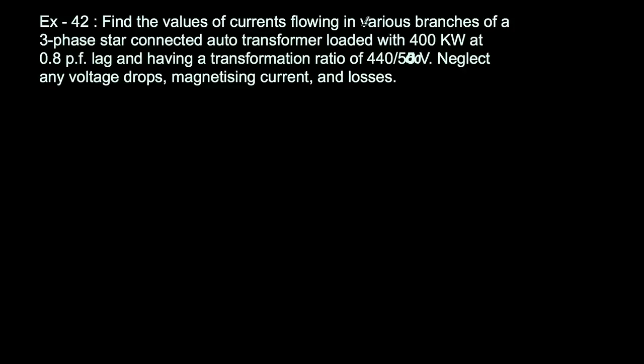Find the values of currents flowing in various branches of a three-phase star-connected auto transformer loaded with 400 kilowatt at 0.8 power factor lag, having a transformation ratio of, so you notice this is a step-up transformer. Neglect any voltage drops, magnetizing currents and losses.